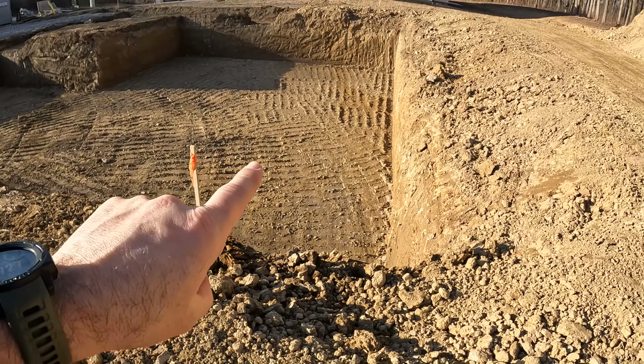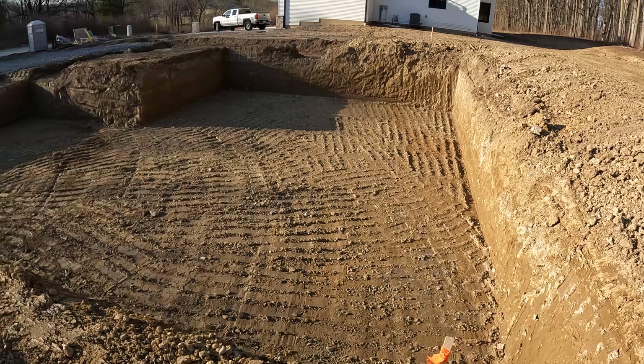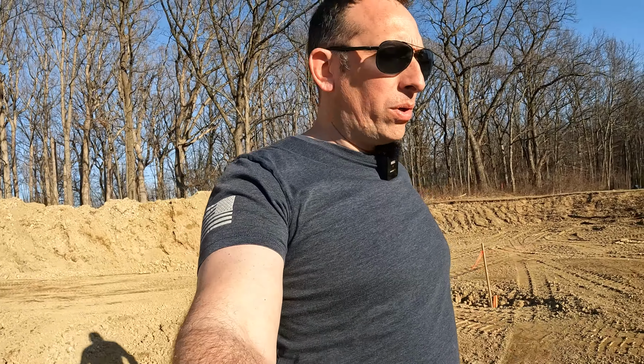So one other thing that's going to happen before we pour our footings: we're going to get them formed, get the rebar in them, everything's going to go in, and then we have to get the county inspector out. He's going to do a quick footing inspection and make sure that we have good solid clay down below the footing where we're going to pour. We of course check it ourselves before we do that, but it's just county regulation. Got to do it. And I think most places are going to require that inspection. But as always, make sure you check with your local building commission on what inspections are required. You don't ever want to miss one.